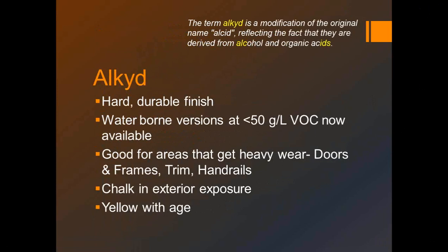Well, I'm a real fan of the DTM acrylics. But as one of the listeners asked in terms of cold temperatures, this would be a good time of year to take a look at the DTM products and not to overdo them. Interior, they're great year-round. The alkyd products would be good this time of year. It'd be good pretty much any time of year.